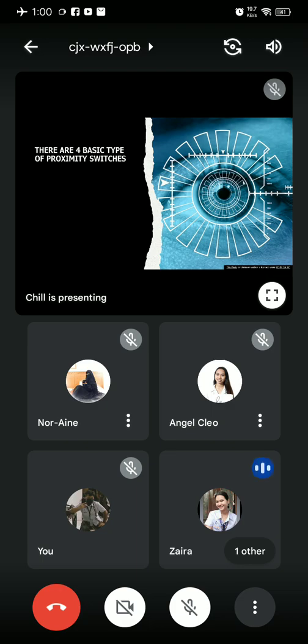And proximity switch is a term often used interchangeably with proximity sensor, but the two should not be confused, because a proximity sensor is a non-contact component which detects the presence of objects within its sensing range, while a proximity switch is a specific component which opens or closes the electrical circuit when the sensor detects the absence or presence of an object.